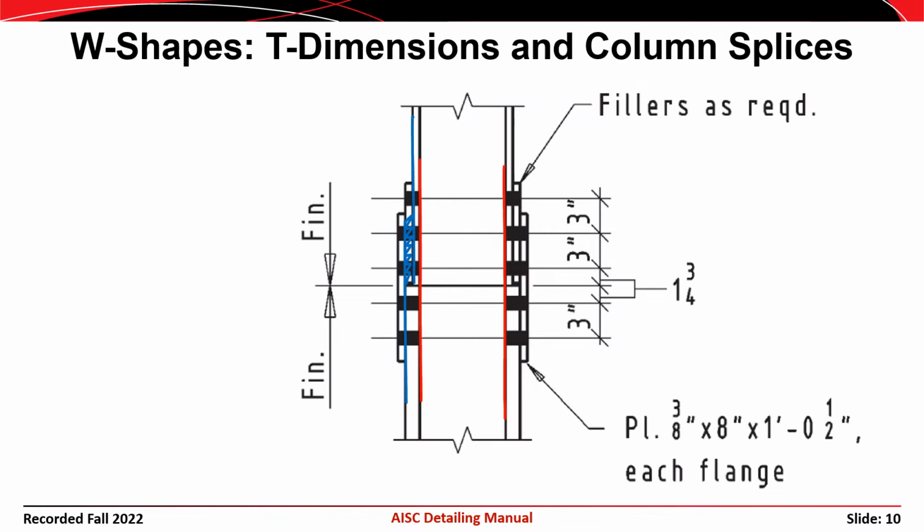So you use an extra plate of steel, an extra piece of steel, and you would call that a filler or a fill plate. And you use those basically just to accommodate gaps that arise when you join different members together.